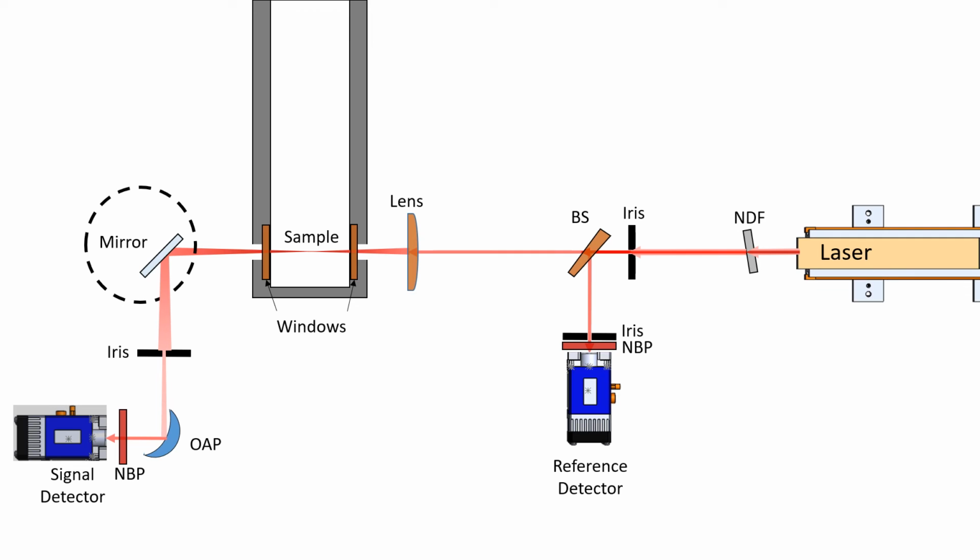The reaction in the shock tube will give off infrared light, some of which will come out of these windows along with the laser. The closer I place my detector to the window, the more combustion-induced scattered infrared light it might capture. I could just place the detector in front of the window a large distance away, but I'm limited by the geometry of my optical table. I can achieve the same path length by turning the beam a few times.